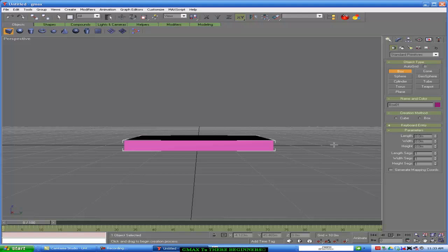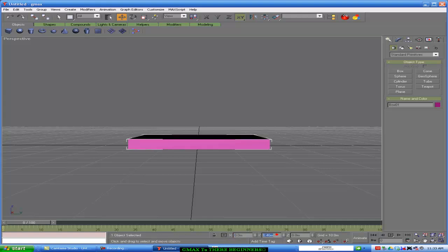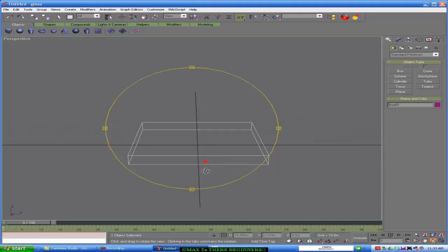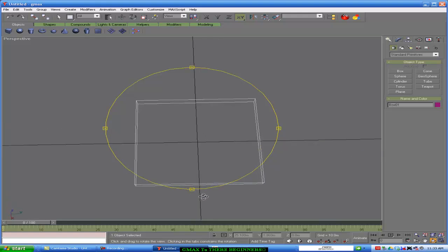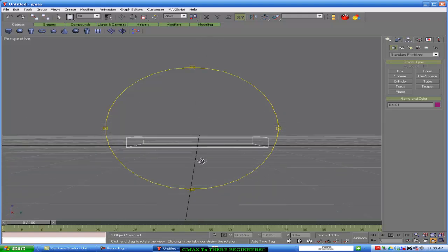Remember the one tool I told you at the top, the move tool? Well, we're going to click on that now. It has the little arrows around it, and it lights up orange when you click on it. But then I want you to focus your eyes down here at the bottom where the X, Y, and Z is. We're going to put a 0 in the X, and a 0 on the Y. And what that did is put our deck dead center on the grid, and that's where we want to be.